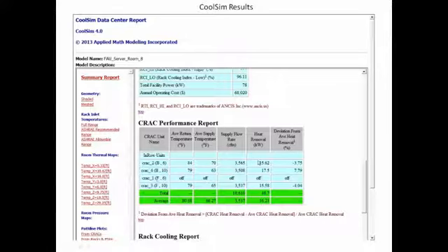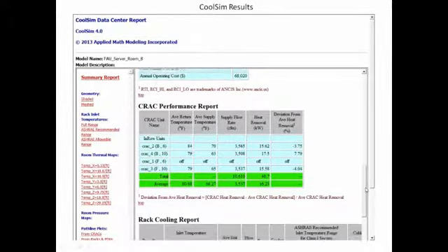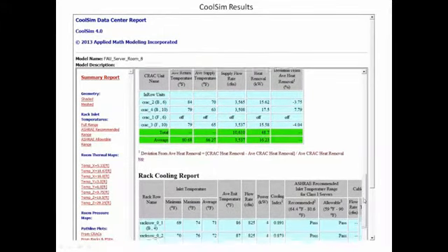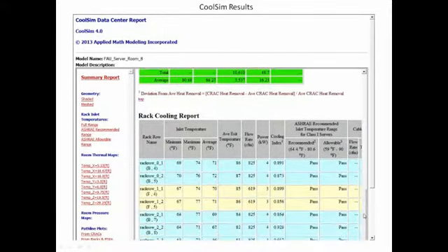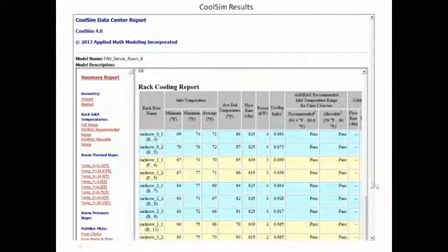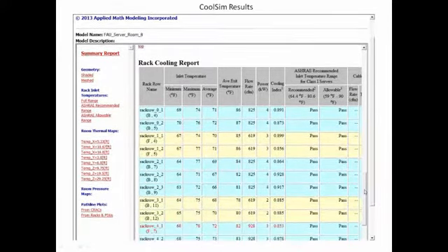But the total heat removed is really fairly low compared to what those units can handle. Those units can handle 25 kW apiece. And here we're only pulling 15, 16, 17 out of them, which means their efficiency from an energy point of view is going to be low. These units always get more efficient as the amount of heat rejected increases. I guess the other way to say that is there's a certain amount of overhead associated with driving them that is just plain there.